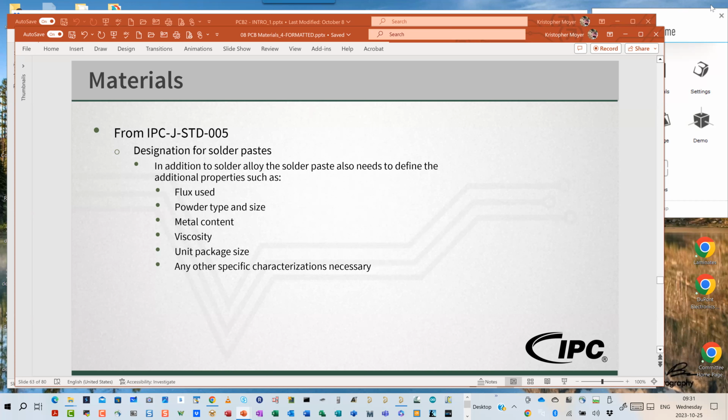No, it's not. It's going to put even more on. The way wave soldering works, they literally spray the entire surface of the board with flux, then it goes through the thing. You've got to wash it more after wave solder than you do after reflow solder. Okay. I just wanted to get some backup from the experts.